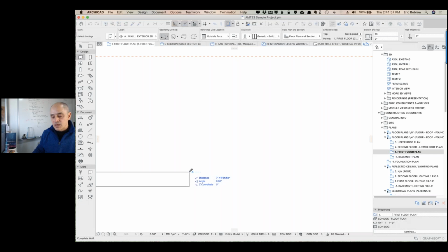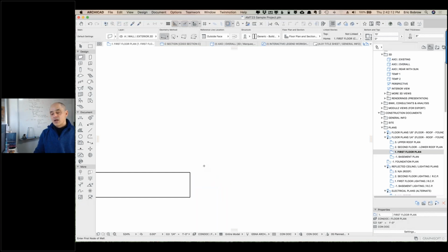And even then, when you zoom in, you may find that it's hard to get it exactly at that number. And so this distance may be off by some fraction. So that's off by 1/6 of an inch, so about 4 millimeters. Obviously not very much in terms of construction practice, but these sort of errors can multiply as you are working.